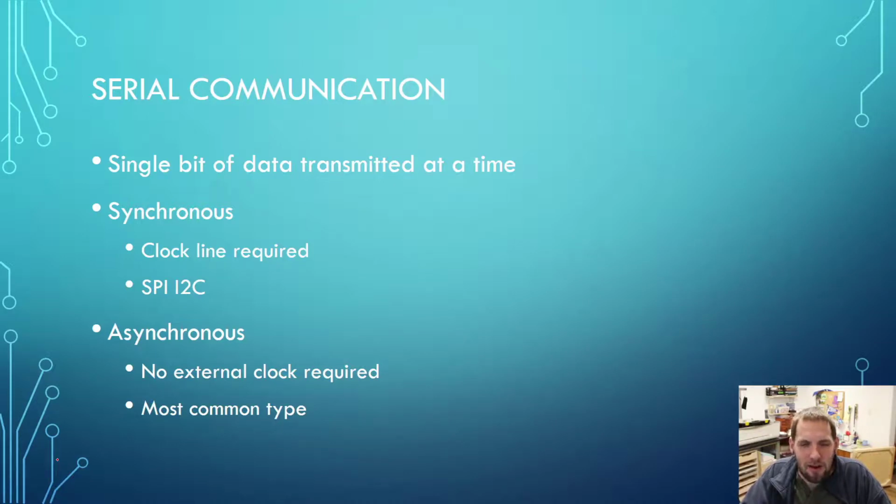So you're going to be getting some misinformation. You're going to be receiving multiple bits high or low. Let's go simple. I'm going to send at 100 bits per second. You're going to receive 1,000 bits per second. So you're going to receive 10 ones for every 1 one I sent. Or you're going to receive 10 zeros for every 1 zero I sent you. So it's a big difference there.